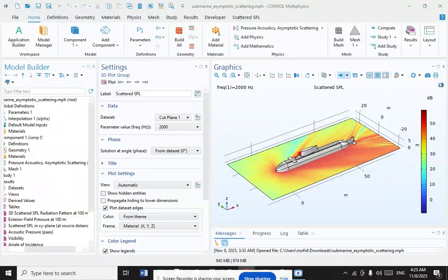Target strength is a metric that can be used to calculate the size of a sonar target. The majority of submarines have absorptive materials applied to the exteriors of their bodies to reduce the strength of the backscatter signal. When only one angle of incidence and frequency are considered, the model computes the force imparted to the target.